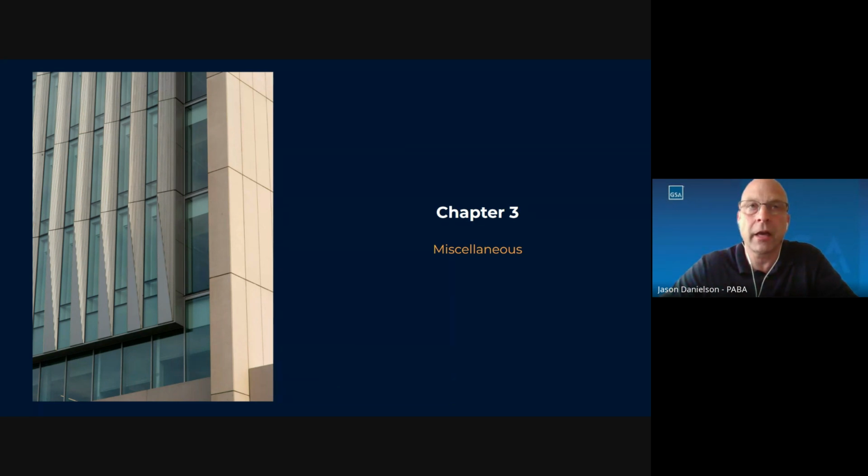If you look at, I don't have an image in this presentation, but I've had it in others, if you look at the net zero pyramid, number one is programming, but right above that, as far as bang for your buck and what you really need to be focused on, is improving the building enclosure. By improving your building enclosure, you can potentially reduce the size of your equipment, and HVAC and some of these other equipment can potentially be downsized, and you can see some savings as well as embodied carbon reductions.